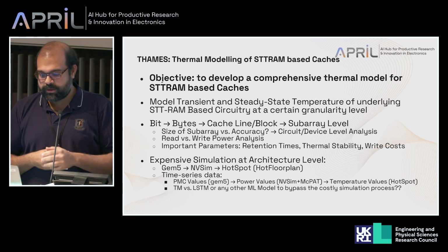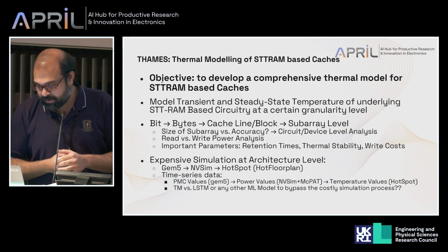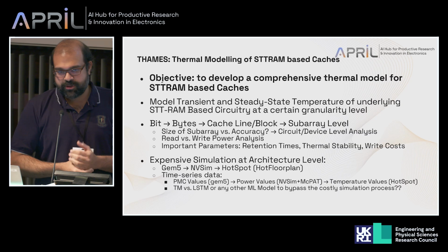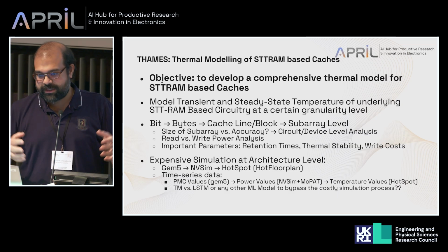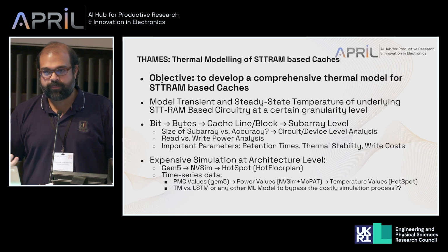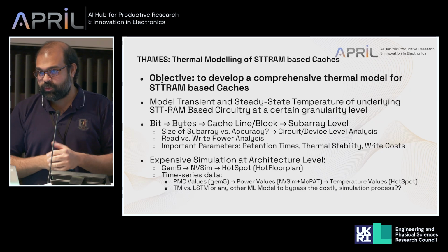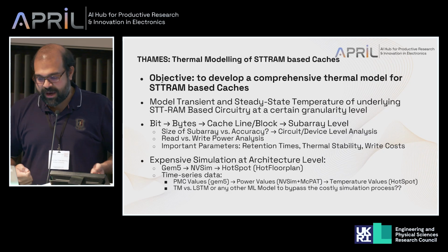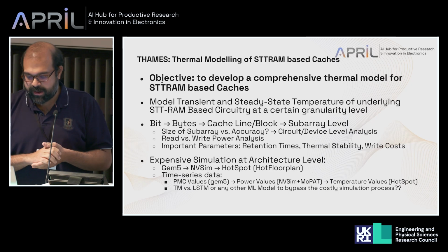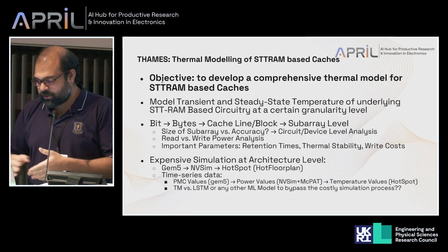Along with that, we are also doing read versus write power analysis, followed by some other parameters, as I mentioned earlier. Okay, so for expensive simulation at the architectural level, we started with GEM5, which is a full system simulator that can simulate the cache memory all the way from the processor. GEM5 will generate performance monitoring counters data that will be fed to the power model of the non-volatile simulator, NVSim, from where we can also generate the area, through which we can prepare the floor plan by using another embedded simulator called HotFloorplan. And we have customized the HotSpot simulator to generate the thermal traces.